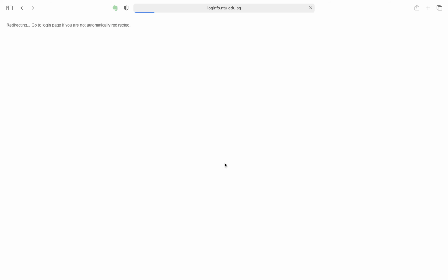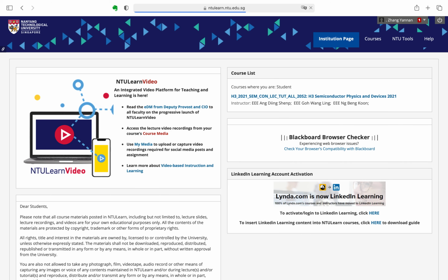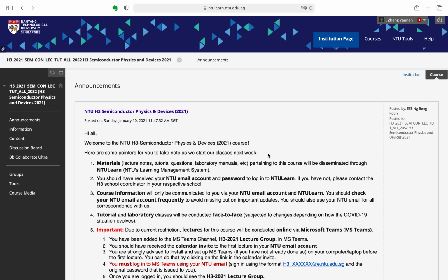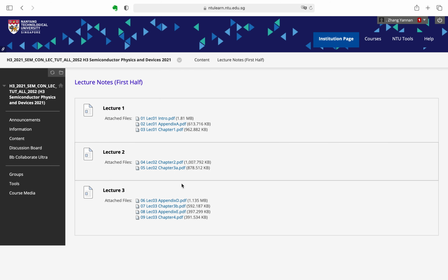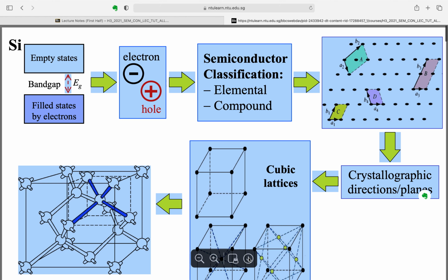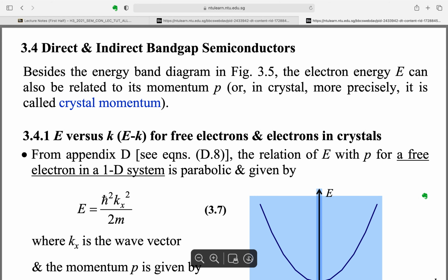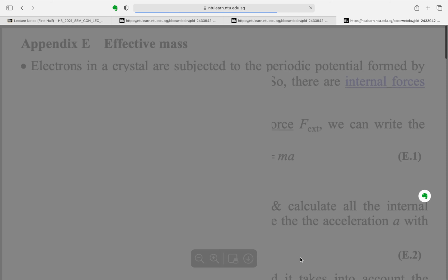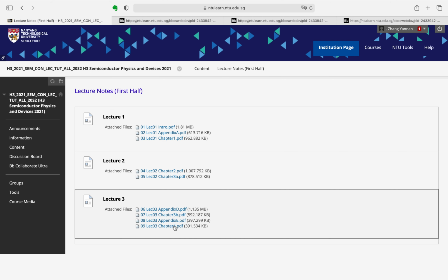We also covered the description of crystals. We mentioned the lattice structure, which we understand as a framework of points in space, where if you put atoms at the lattice points, you can create the semiconductor crystal. And in this lattice structure, we can identify representative regions or representative units, which if you duplicate them and stick them together, you get back the semiconductor crystal structure.